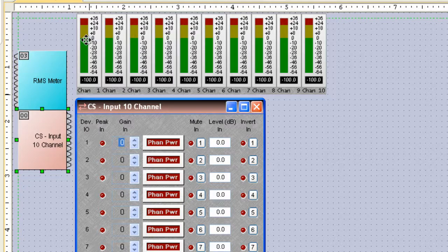The bottom line is we want to give our analog to digital converter the most signal we can to allow it to get a good sample of the audio, and to get the signal to noise ratio, the signal, as high as we can above the noise, yet leave us a little bit of room before we run into our ceiling. In the Nexia we have 24 dB of headroom. About 85% of all calls to our technical support department can be solved by just setting this properly.